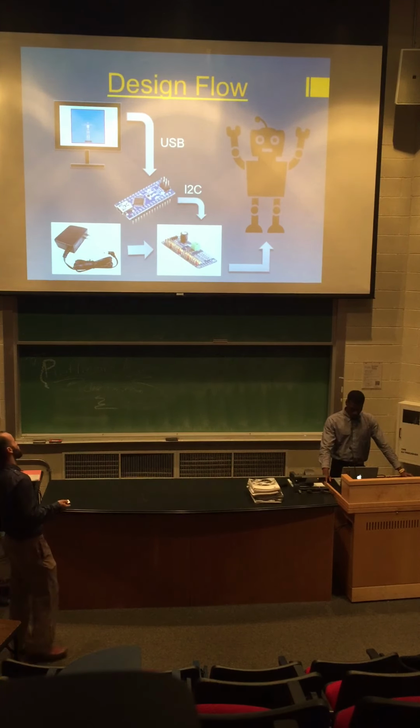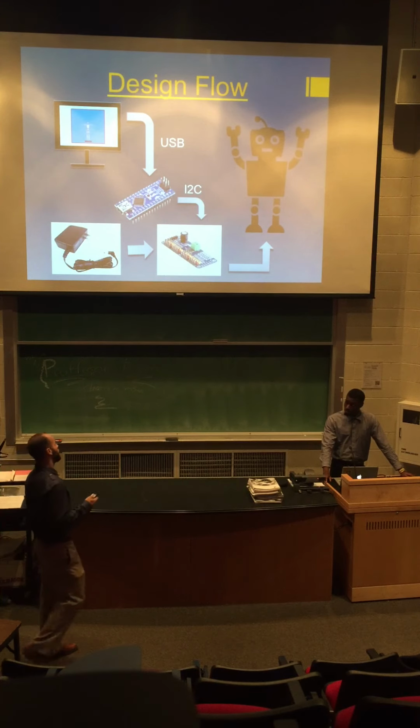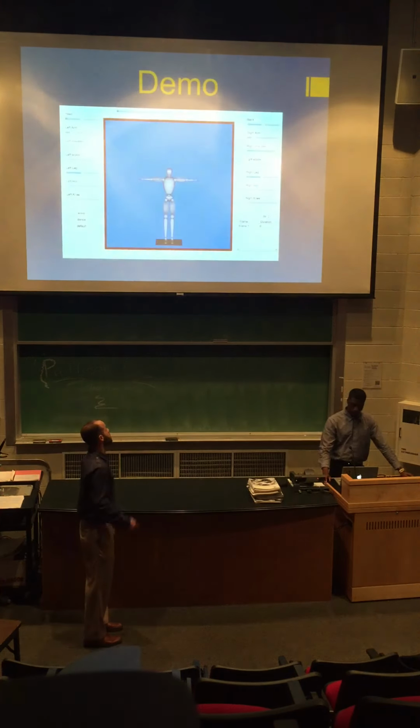The servos take about 600 milliamps each, so we needed that additional power supply. This is the 5-volt, 10-amp power supply, and this is physically connected to the servos that are mounted in the robot that we're going to create. And we have a demo.